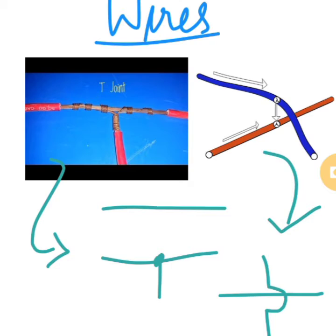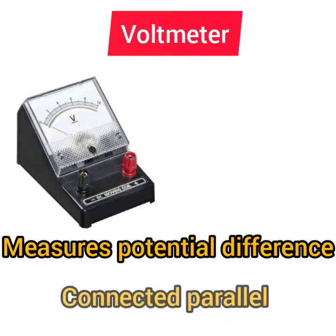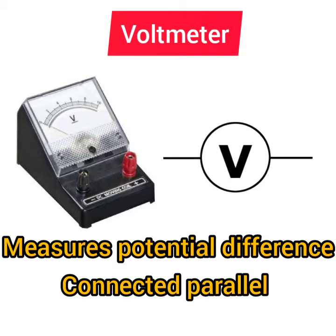Voltmeter. The potential difference in a circuit is measured by means of an instrument called a voltmeter. A voltmeter is always connected in parallel across the 2 points where the potential difference is to be measured. This is because a voltmeter has a high resistance so that it takes a negligible current from the circuit. The symbol for a voltmeter is drawn by drawing a circle and writing the letter V inside it.